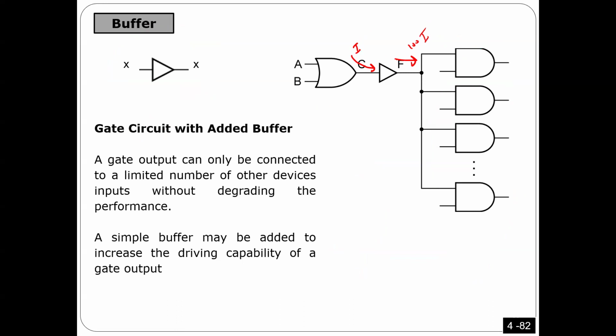Because where should this current come from? It has to come from somewhere. You understand what I'm saying? There is nothing that can take 1 I and give you 100 I, because the 99 I has to come from somewhere. Actually, this one has a bias. This bias is similar to what you do with the chips when you connect the VCC and the ground. That's what we call a bias. So this current is coming from this bias, not from the input here.